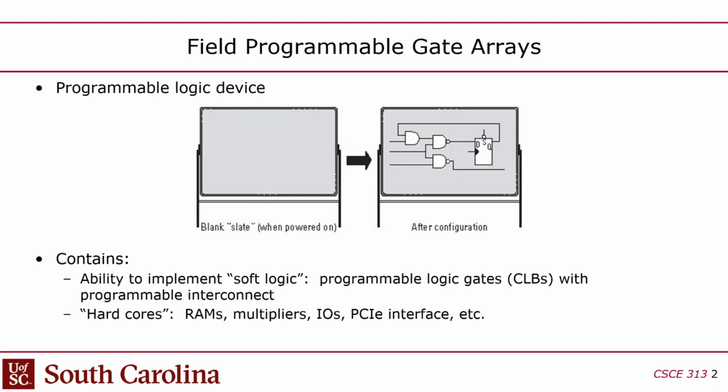And plus, the other thing in this class is we want to focus on control theory. A lot of controllers are implemented on FPGAs because they're deterministic. You know exactly what they're going to do in every cycle. Whereas with a CPU, there's uncertainty introduced with the cache and the page table and interrupts and other things going on. It's hard to know. It's hard to get real-time constraints.